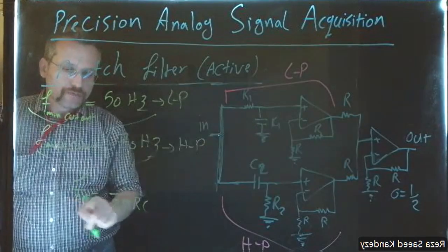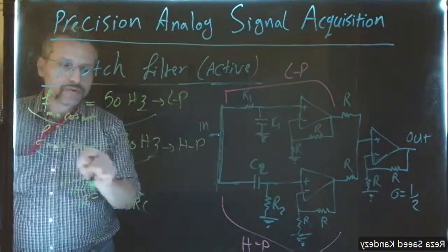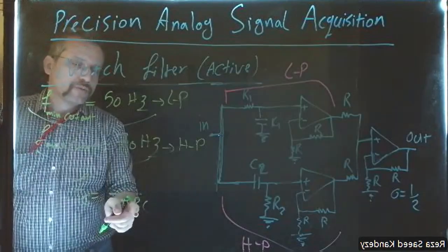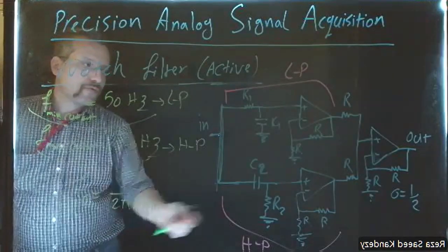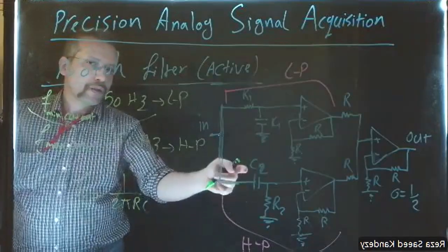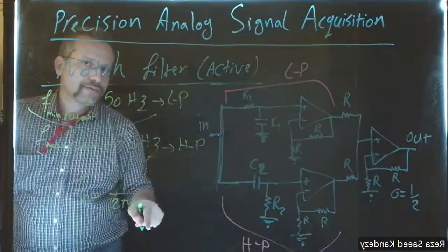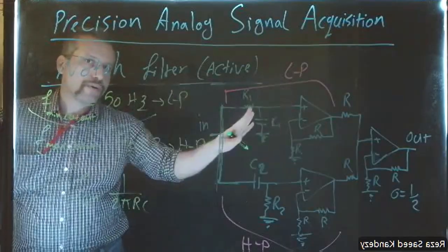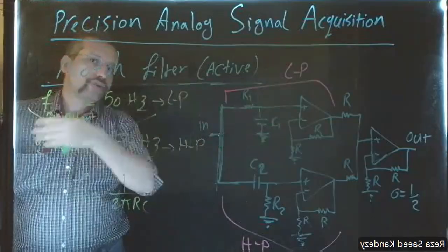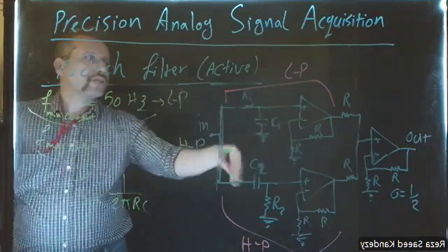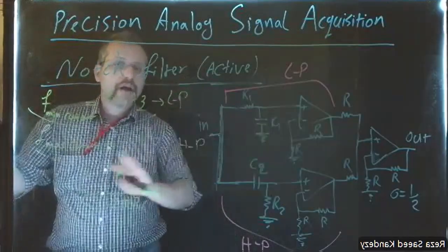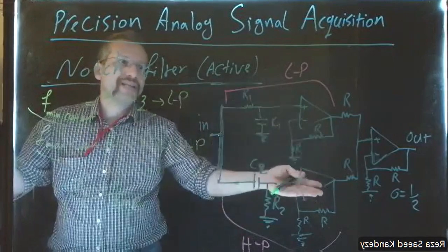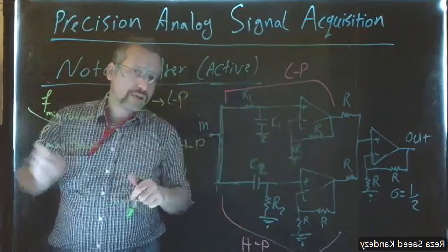Then you put the cutoff frequency equal to the max for the high pass, 70 hertz. You assume a value for R, and then you find the C2 for the high pass filter. That way, it's already designed. Very simple. Now, we can go to the lab and see if this circuit actually works. Again, I'm not going to give you the values. It's your job to design that, but this is how we can do it.